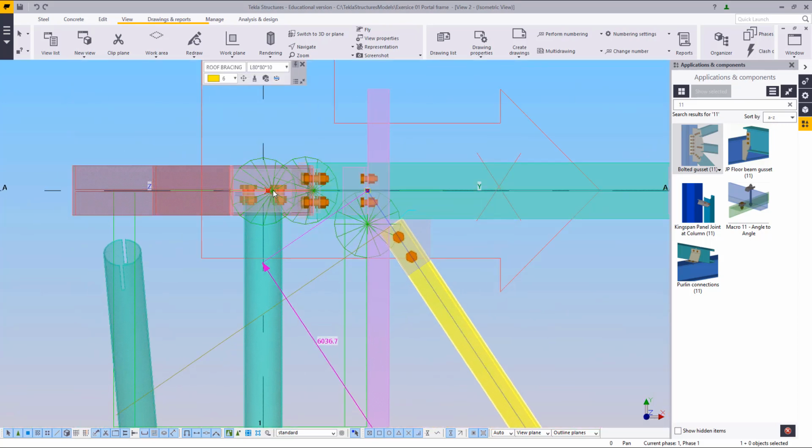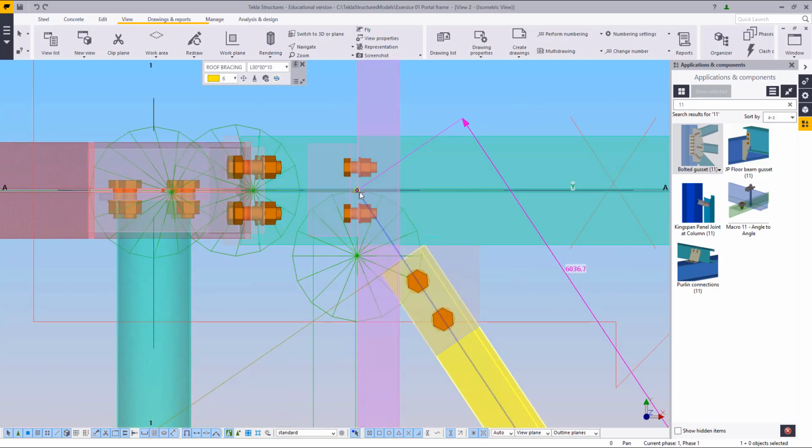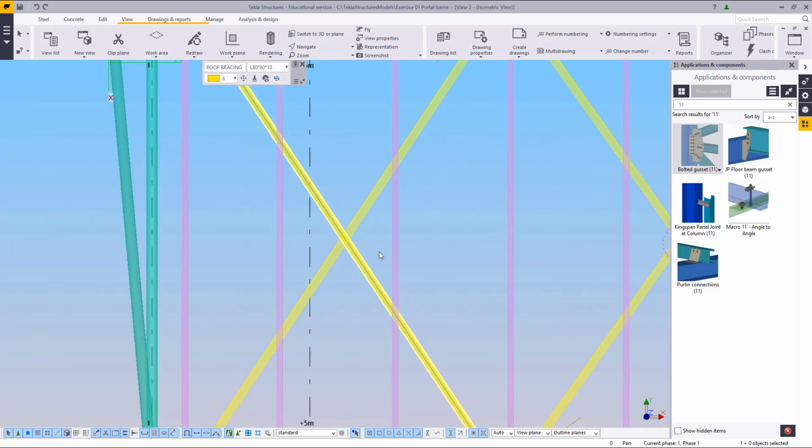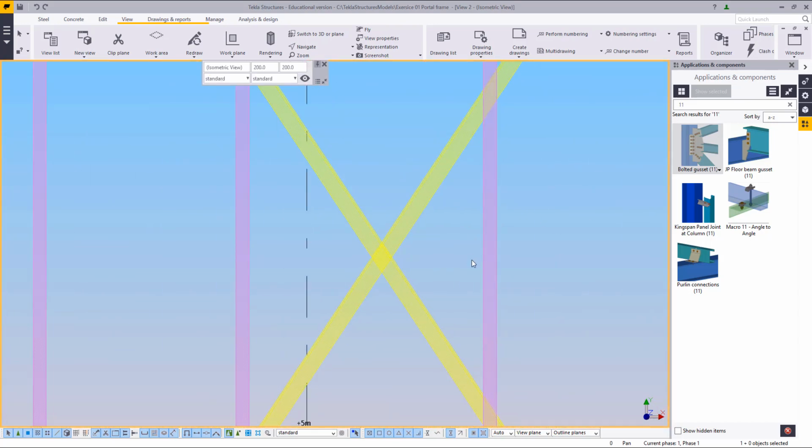So the SOPs do not necessarily have to be here at the edge. Usually they're either on the purlin's back like this, or they can just be somewhere in this vicinity. The positioning is not as rigid as it is with some of the other bracings.